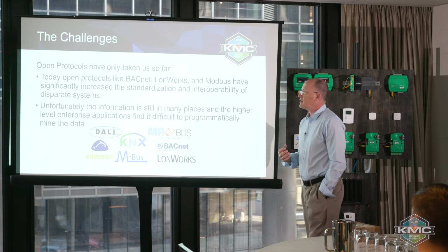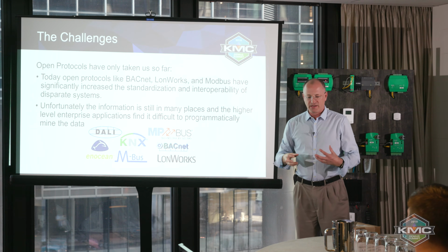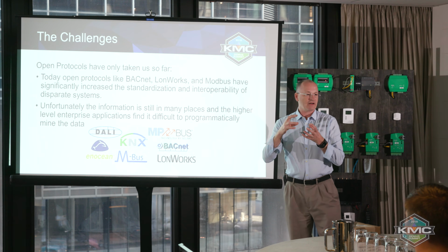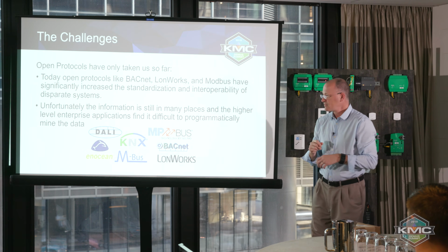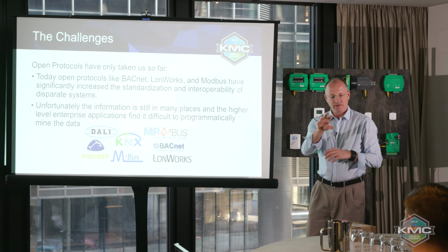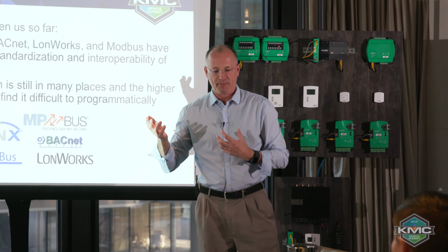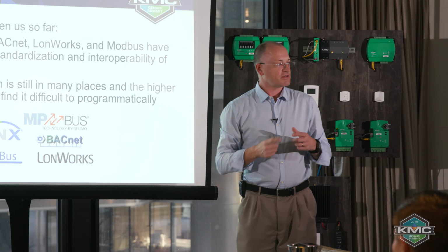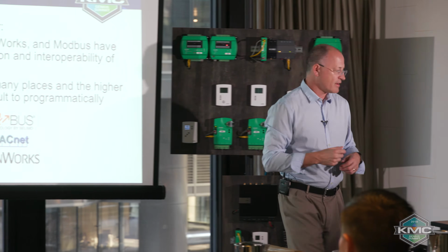And so certainly open protocols like BACnet, LonWorks and Modbus have significantly standardized the device level part of the architecture, and aggregators like Niagara have done a good job at the supervisory level. But unfortunately, that information is still in pockets depending on where you are in the architecture. We can't just go out and get an app and then have it magically give me all my energy reports. There's a mapping and an engineering effort that goes along with that.